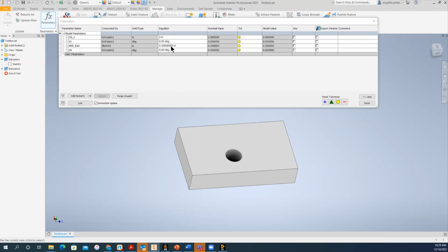The only other thing that you need to do on your end, or rather, inside your CAD platform, is to make sure that you have the prefix DS or ANS next to your parameter names. DS and ANS basically indicate to Ansys that these are the parameters that are meant to be imported into Workbench when you try to transfer your geometry. So if you did not have these prefixes, then Ansys wouldn't know which to import. I just had one DS and one ANS for the sake of example, but you could only use DS or you could only use ANS.